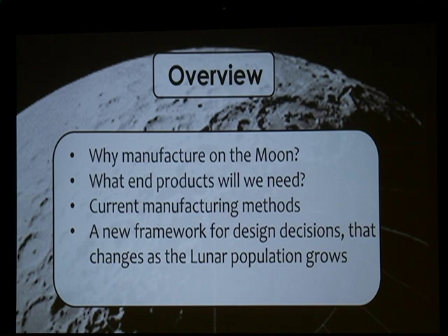A previous speaker talked about vacuum being a resource. The highest quality steel you can produce is produced in vacuum. So vacuum casting, you don't get any bubbles, you don't get any oxides, and if you want to roll that stuff out into hot rolled steel on Earth, you'd then have to clean off the scale before you got a clean billet of material. In space, that just doesn't really happen. The most you need is basically a garden shed to keep dust out, and you can produce all the clean iron that you want.